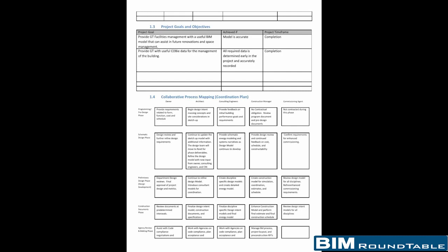We need to know if you're wanting to use the model for quantities, especially if it's a concrete job. We'll definitely want to know that ahead of time, as a structural engineer, that you're going to be using it. Concrete especially. Steel you're going to model pretty accurately anyway. With concrete, you have to jump through some hoops in Revit to get it as accurate as you need it to be for quantity. Which kind of goes back to our ins and outs. Yes, exactly.